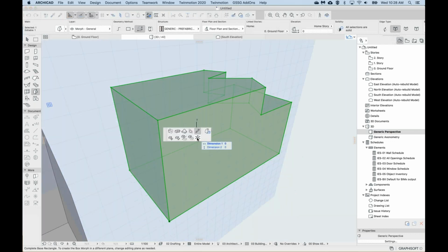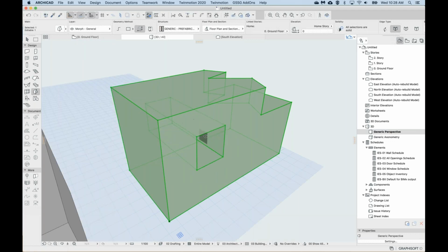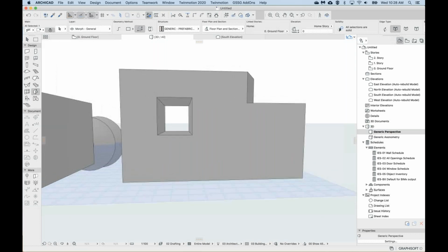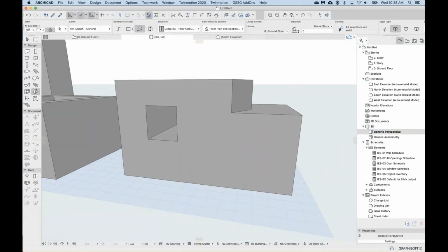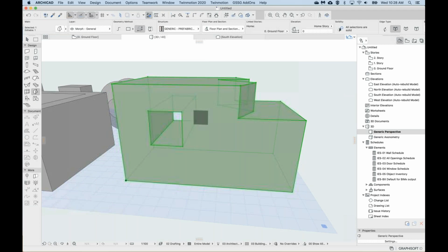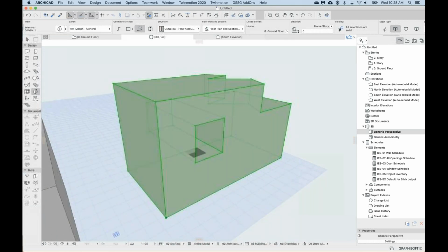So with this morph selected, click on the side surface, pencil, draw a rectangle on that surface. Then I'm going to push that, and then hover my pencil over one of the nodes on the other side. Just snap to that, click, and that will create a hole. So it's quite similar to this method. We just have to make a box the same thickness as this morph shape.